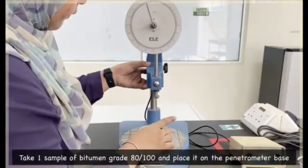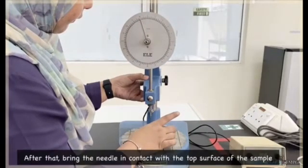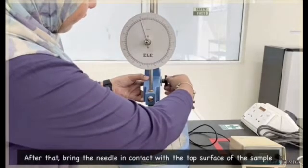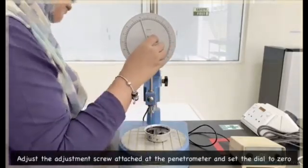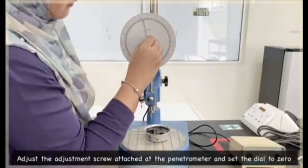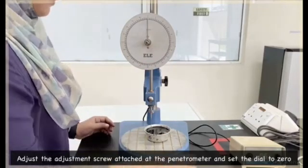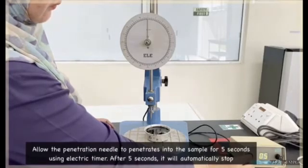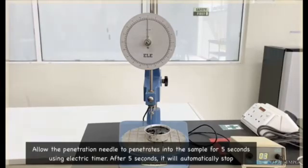Take one sample of bitumen grade 80/100 and place it on the penetrometer base. After that, bring the needle in contact with the top surface of the sample. Adjust the adjustment screw attached to the penetrometer and set the dial to 0. Allow the penetration needle to penetrate into the sample for 5 seconds using the electric timer. After 5 seconds, it will automatically stop.